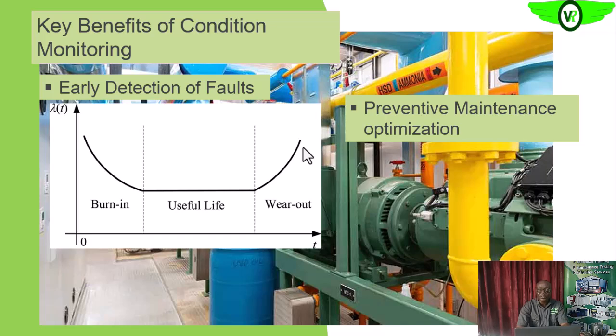There are some that you cannot allow to run to failure. For those, the preventive maintenance program, which is time-based, may be the most feasible, either because it is cheaper, or you have the in-house technology and capability to do it, or it will be less expensive for you cost-wise. Okay, then you can also have the condition monitoring technology.